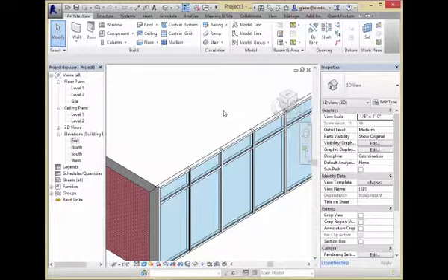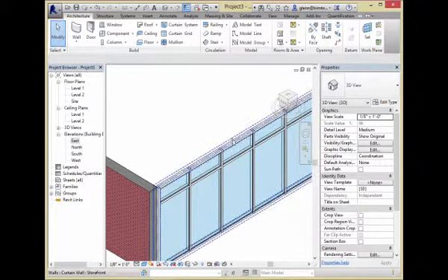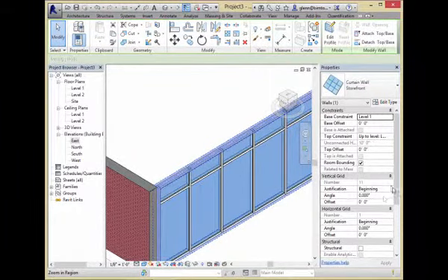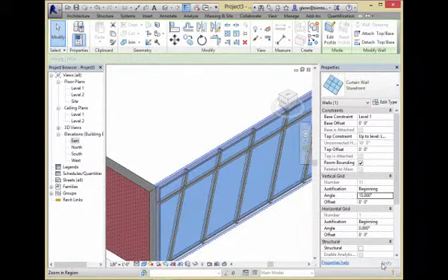So all these types are really just defined by patterns. If we look at the wall, you'll see the pattern actually has, or the wall, the curtain wall has a couple different sort of parameters that you can adjust. One of the ones that's kind of interesting, these are also the same, top and bottom, that's kind of all about the same. But one of the pattern choices that are sort of interesting is the notion of, should you put an angle on the grid? By default, everything is perfectly horizontal and perfectly vertical. A lot of newer buildings sort of play around with that, though. So if you, for example, want to have those verticals not be vertical, you can put some sort of dimension in there, like 15 degrees. It'll rotate them over for you.